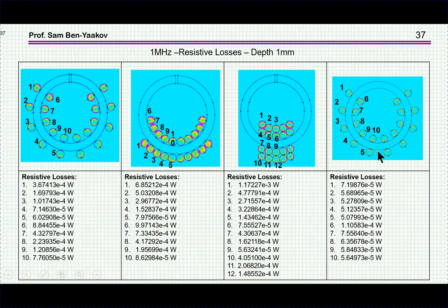the best. But core losses will be very high if you use it for resonant converters. However, for the case of regular PWM converters, in which the delta I, that is the ripple current, and therefore the delta B expected in the core is small, the iron powder core will have advantage because the losses due to the skin effect and in fact the proximity effect will be much lower, considering the fact that the magnitude of the AC component of the current is much smaller.